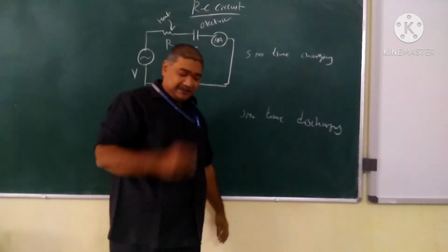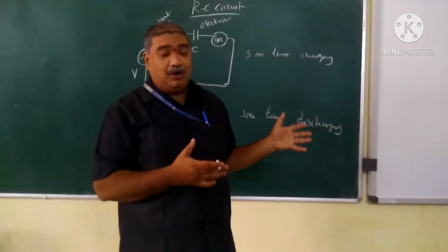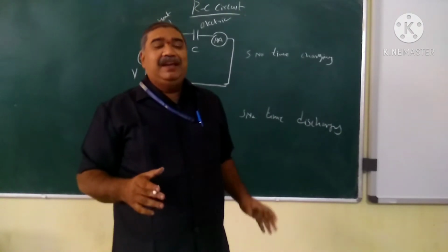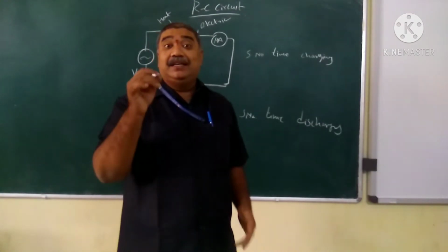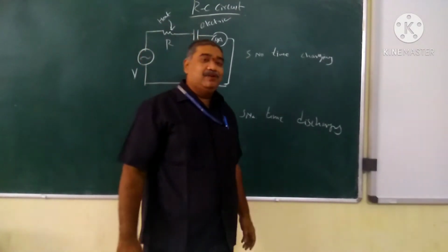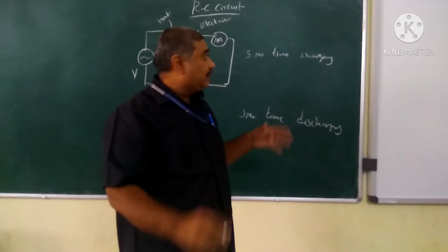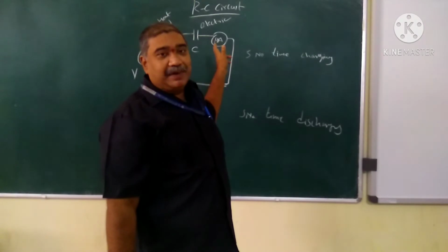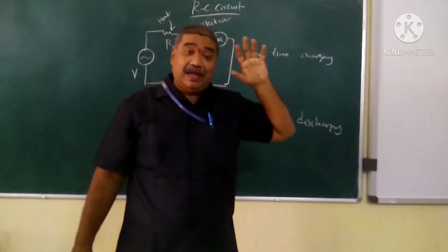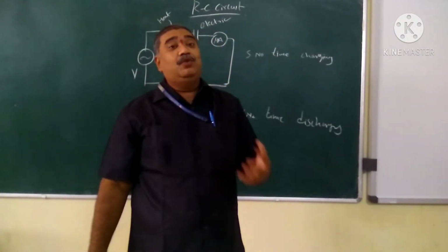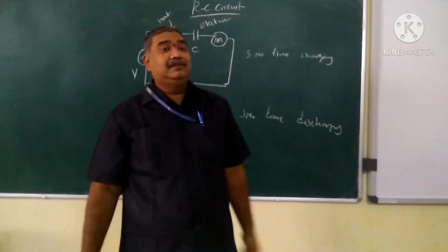To know this, I will give you a simple example. We already have this example. For instance, we have water pumping motors as well as fans. Immediately after the fans or water motors are switched off, the electricians never touch a capacitor. Why don't they touch a capacitor? Because immediately after switching off these fans or motors, a little amount of electric energy is stored in the capacitor. If you touch a capacitor immediately, we receive a shock. So what do the electricians do? They wait a little amount of time before servicing these machines. So we need to find out how much time it takes for this energy to get discharged.